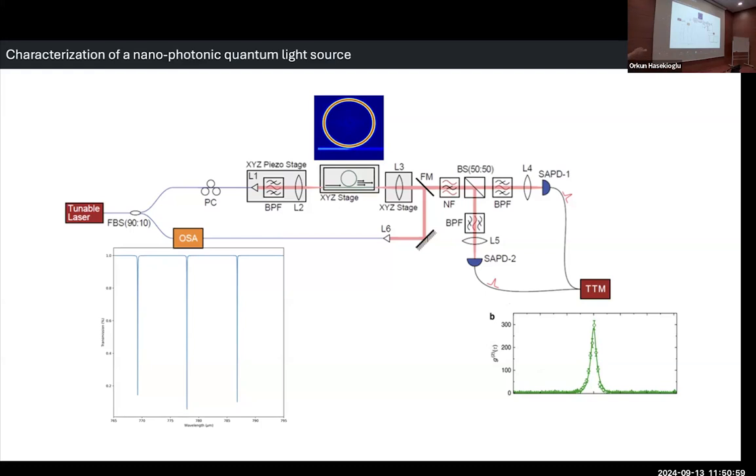This is our, for example, four-wave mixing or SPDC ring resonator chip, placed on some motorized stage. We have some optical components to focus the laser beam onto this chip, and then collect it and send it to some optical spectrum analyzer or spectrometer to get the transmission behavior from this chip and correlate it with the laser, to see if they are in good agreement and if it's the expected result.